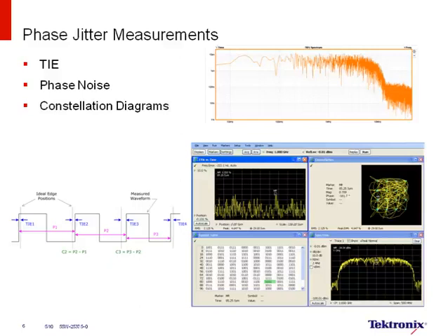So again, the difference here is in this plot, when you make a phase noise measurement, you can very precisely average this plot and know what a tone is, an offset from the frequency. But what you do not have is a trajectory. In other words, let's say you have a 10 hertz offset, but what you don't know is how it's changing with time. And so that's one of the benefits of having a time trend view. So hopefully that answers your question about how these measurements will translate to jitter. And again, if it doesn't, please feel free to email me directly.